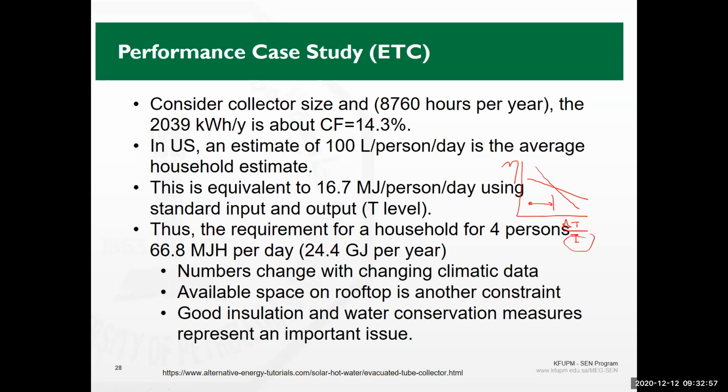Do you have a space on the rooftop or not? If not, then we have to put it on the ground. Putting it on the ground, we have to make sure that it will not be shaded by trees or by other buildings. Not only now, but you should keep in mind that hopefully in the future, no very tall building is going to be erected next to you so that it can shade your collectors. And that's another issue. The collectors have to be well insulated so that you are conserving your energy, not losing the energy just by heat loss to the surroundings.